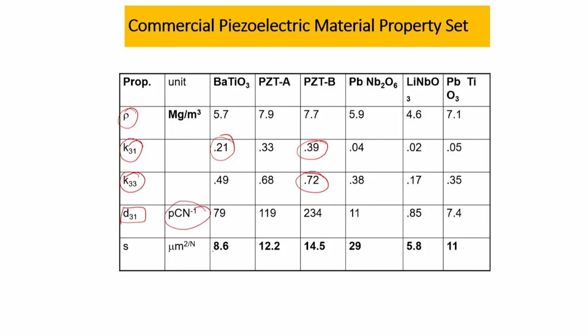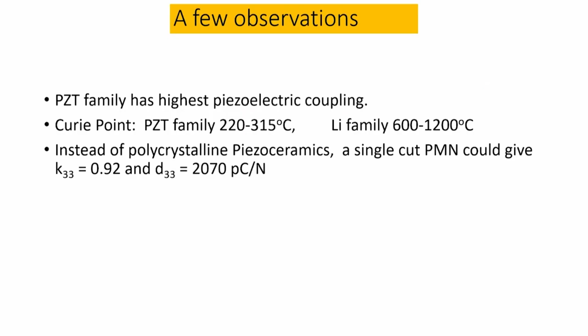And the last column is talking about the compliance modulus of the system. So, this S is not the strain, that is the compliance modulus. So, you can get a comparison of different piezoelectric materials through this table. A few observations you can note here is that the PZT family has the highest piezoelectric coupling, and the Curie point